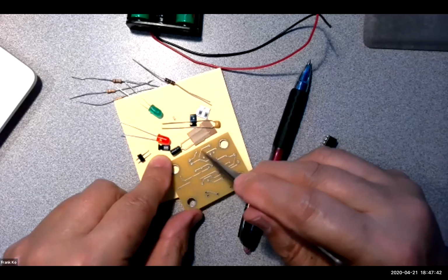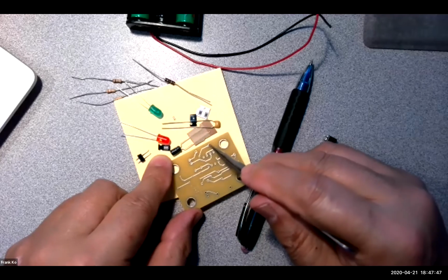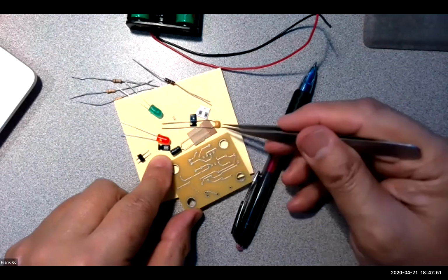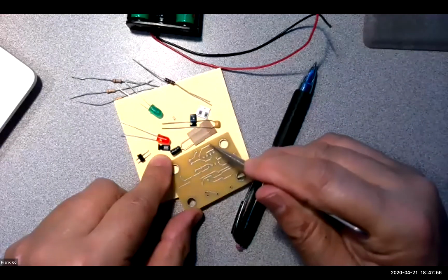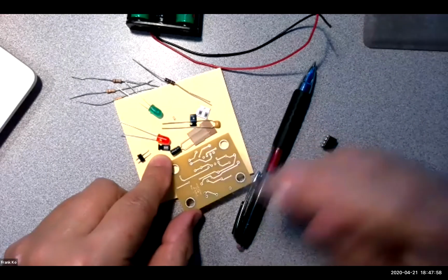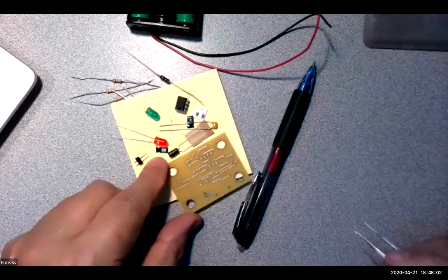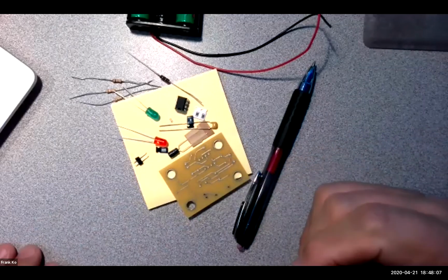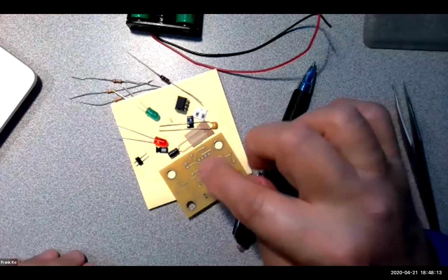You are going to make a repair, and that's a very important skill for technicians to learn in case something goes wrong on the board, like a burnt trace. So it's a great learning experience for you to learn in this particular case. So, don't let burnt traces ever upset you, because burnt traces are repairable by bridging. So the technique is called bridging.